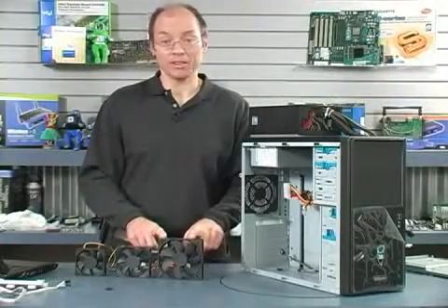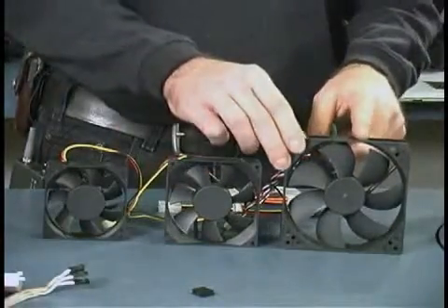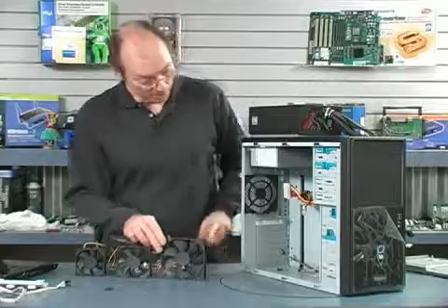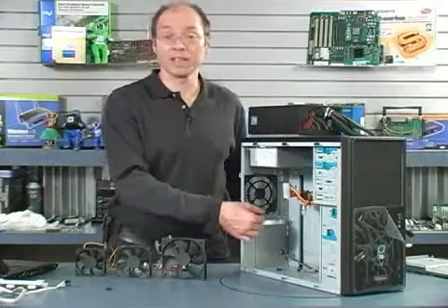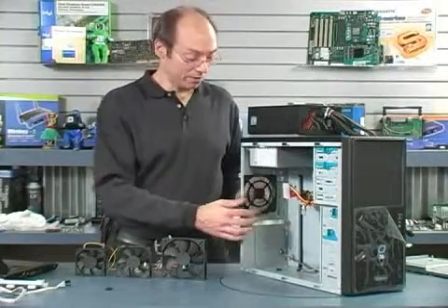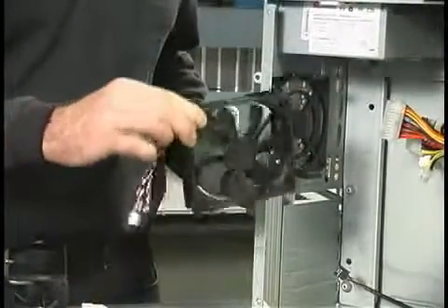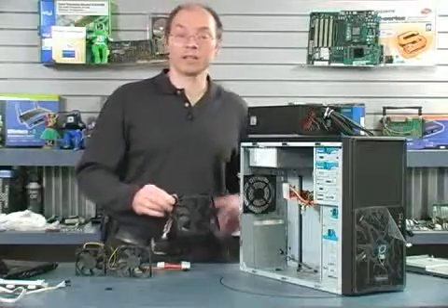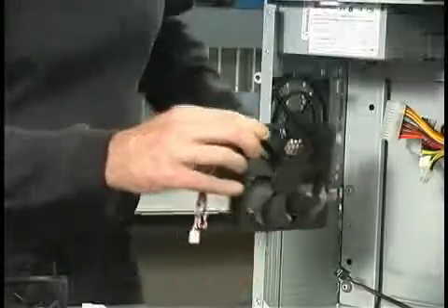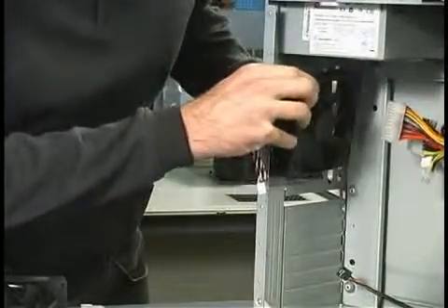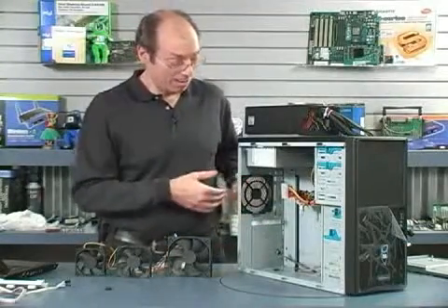I generally won't buy a case unless it has either a 120 or a 92 millimeter rear chassis fan, preferably the 120. This is an example of the 120 millimeter fan, and that's what this case came with. One nice feature about this case is that the fan clips into a bracket that's installed into the case. Once the bracket is screwed in, you can easily snap the fan in and out. Being able to take it out quickly and easily makes loading the motherboard a little bit easier. If the fan ever does fail, you can snap in a replacement very easily. It just literally snaps onto these brackets. So that's one thing to look for: a 120 millimeter fan in the back blowing air out.